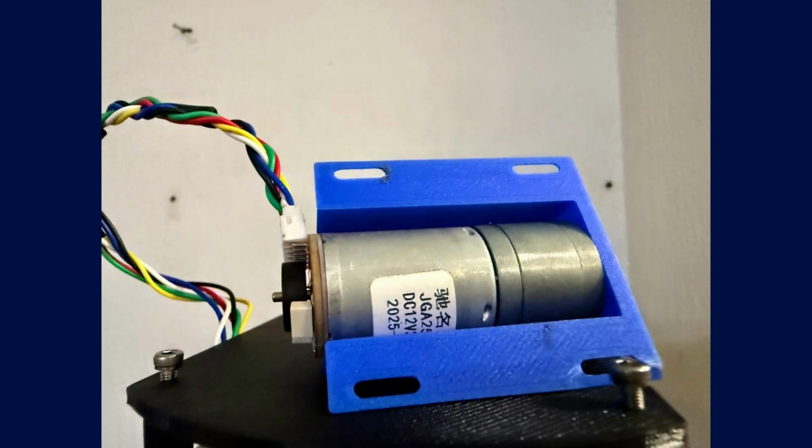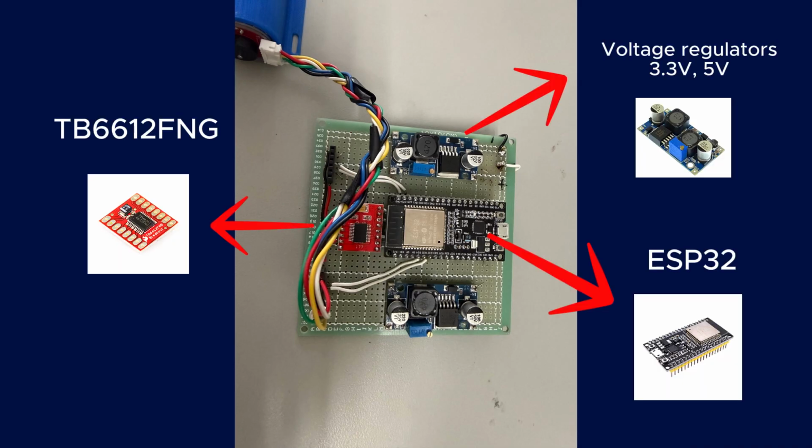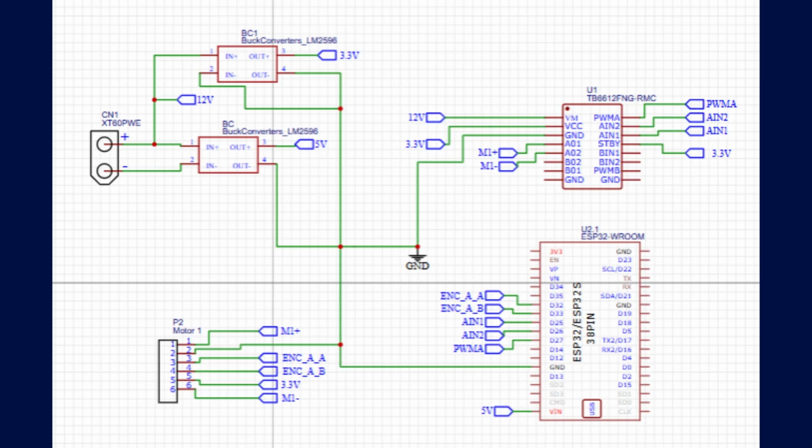For the hardware, we use a GM25370 DC motor capable of 330 RPM, driven by a TB6612FNG H-bridge, powered at 12 volts due to its minimal dead zone. The control is handled by an ESP32, and we use pins 25, 26 and 27 for the direction and speed control, by pulse width modulation. This setup allows us to translate our digital control signals into PWM to drive the motor effectively.